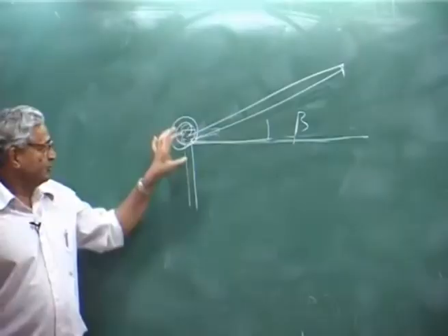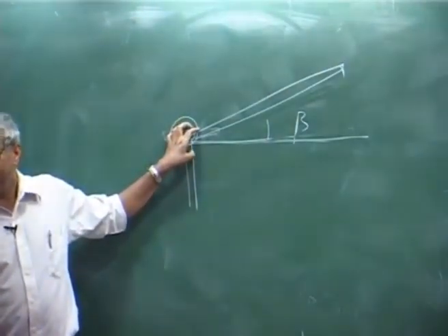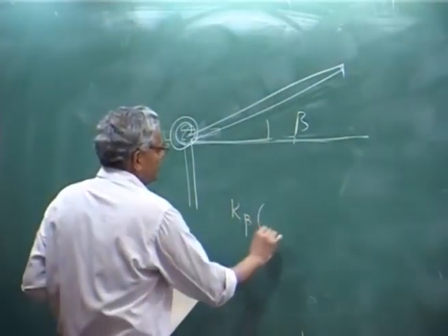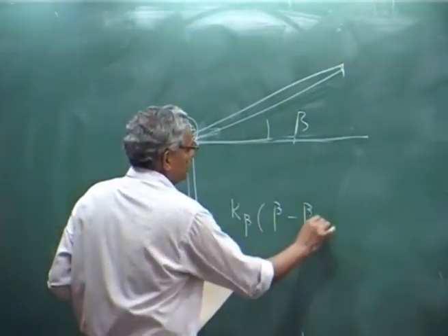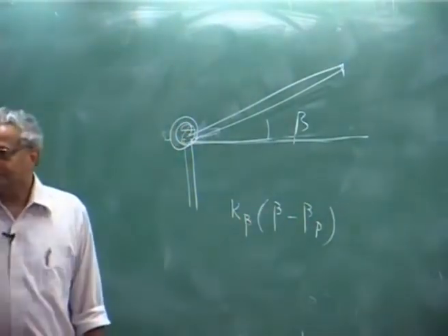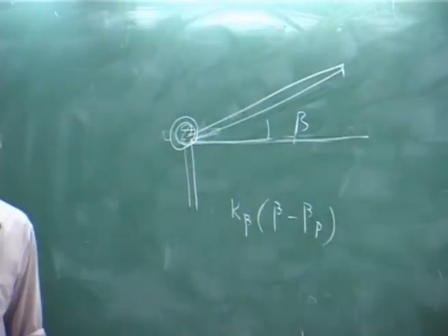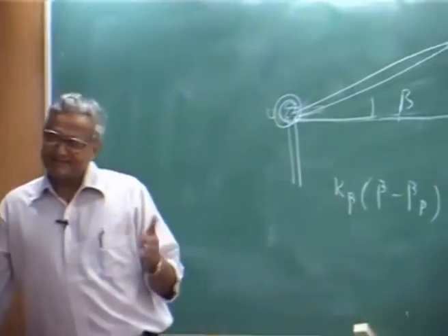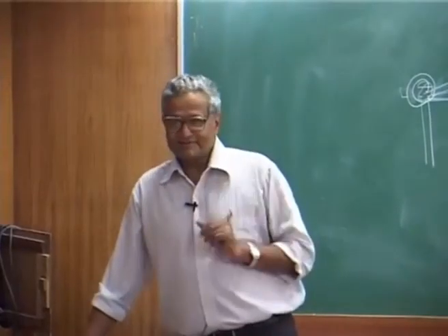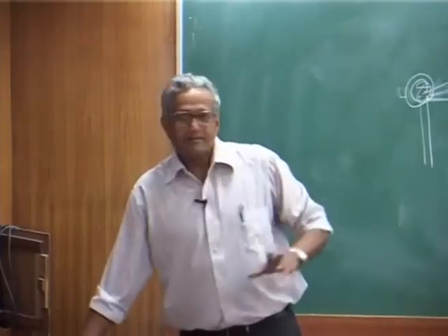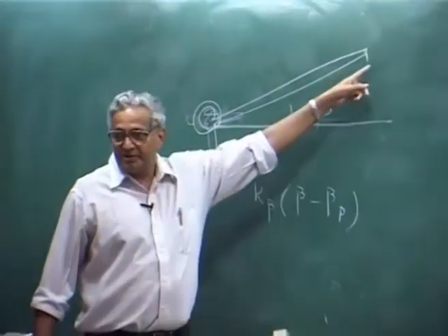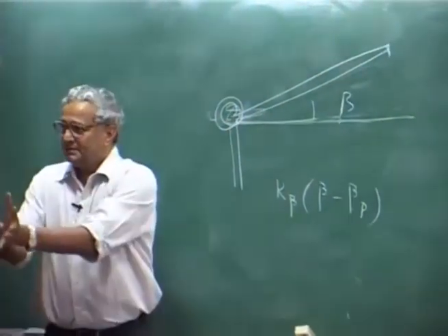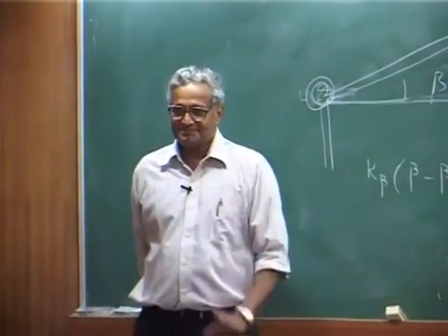Another way is, hey, what is the deformation of the spring? Deformation of the spring is, we said, k beta into beta p. This is the moment due to the deformation, and that is acting at the hub. Now, you see there are two ways of calculating the hub moment, even shear also. If you do vibration, you will learn later. I can get the aerodynamic load, inertia load, integrate the whole thing, come to the root, give that as a moment. That is one way.